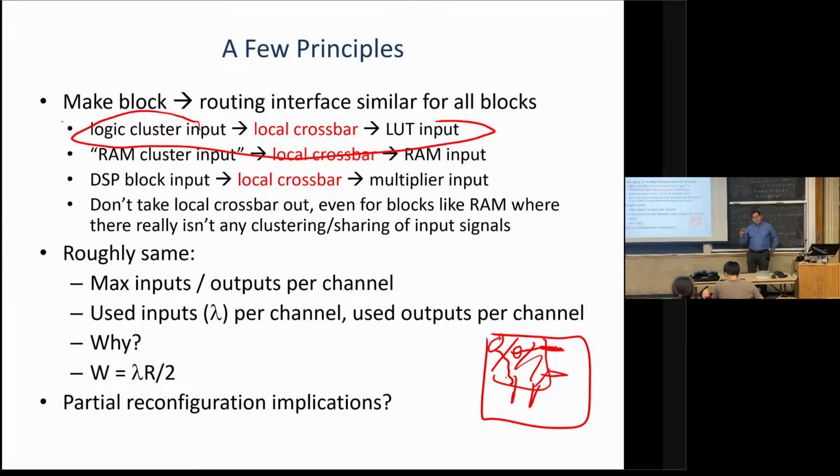But we used to have at least a couple stages of muxing, right? Like get to the connection block muxes that get me to the cluster inputs, and then I have some local interconnect muxes after that. So I just lost a couple of stages of muxing. That's harder, right? I need to get to some specific wire instead of getting to maybe one of 50 wires that would have made it through that mux network. So it's a lot harder.